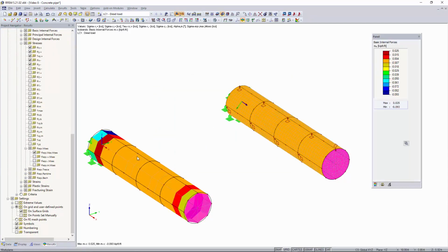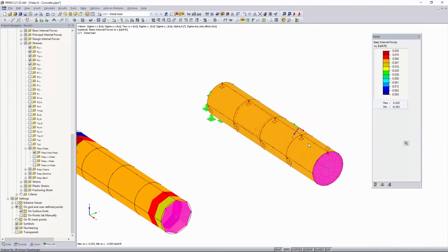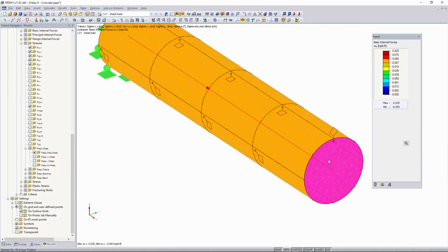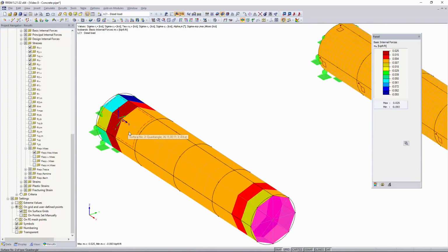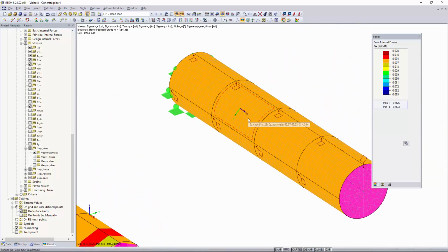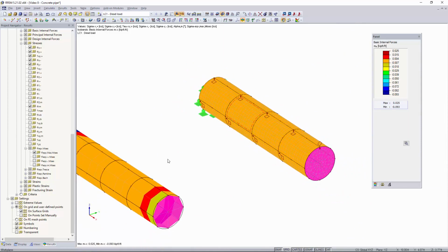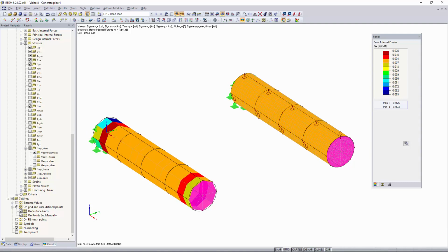Our results are generated, and now you can see how much finer and how much better our model with our smaller FE mesh looks for this. As you can see, we had a 1 foot FE mesh over on this model, and on this model we have a 0.2 foot FE mesh length. And as you can see, that gives us a better accurate representation of our model with a finer FE mesh compared to the more blocky FE mesh over on this side. So now let's view the results.